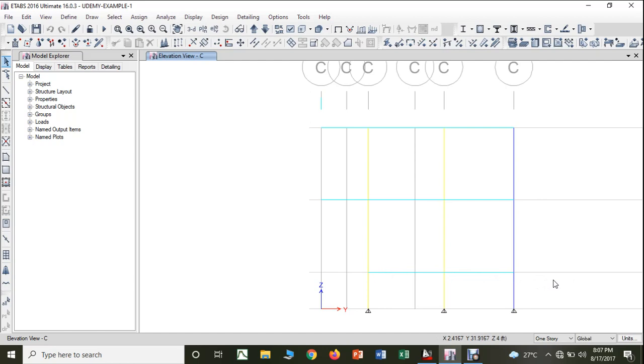Now, one thing I wanted to make very clear is that the load on the plinth beams is very less. Why? This plinth beam will be resting on the soil. The major two reasons I told you why we provide the plinth beam. The first reason is in order to make the column stiff.